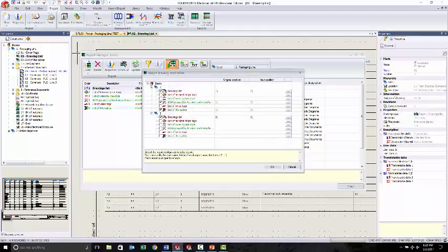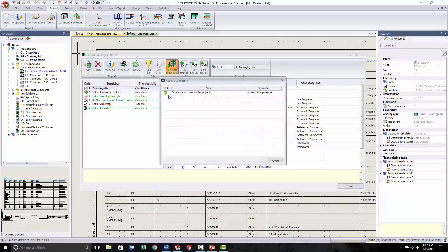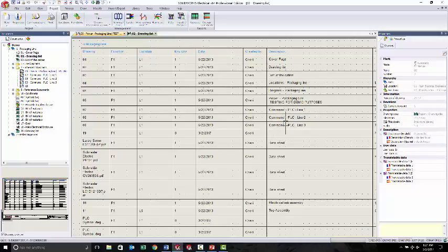Drawing list. Now normally I make the drawing list last, because if you are making it last, then it will actually do all the other updates first and then update your drawing list. But at this point, I added another bill of materials, and this is the problem that you had with your PDF, which is something that we'll look at here in just a second.